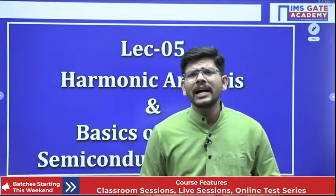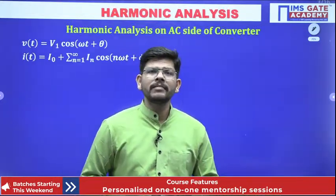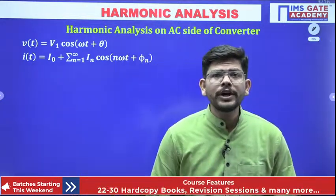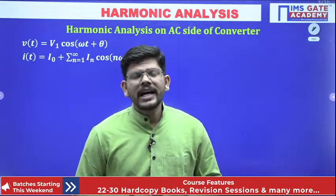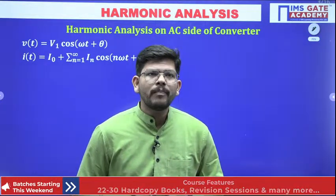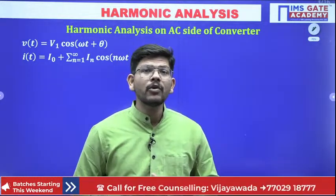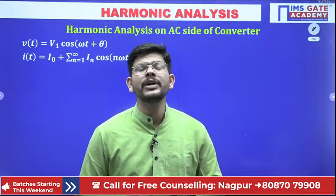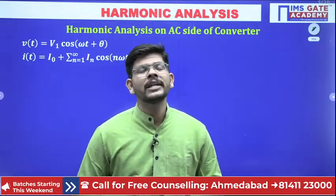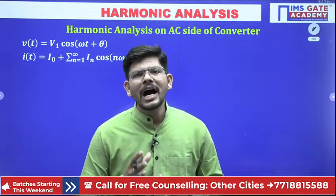So what actually are harmonics? Harmonics are basically multiple frequency terms of the fundamental term. If they are there, they are going to pollute the quality of our voltage and current, or ultimately the quality of power. So ideally harmonics should not be there. But unfortunately, we are forced to have these harmonics when it comes to power electronics, because of the switching actions of the converter.